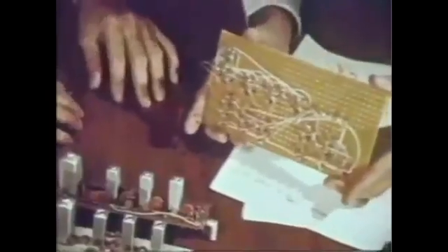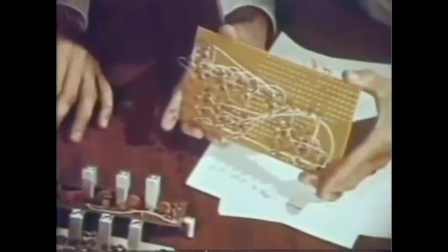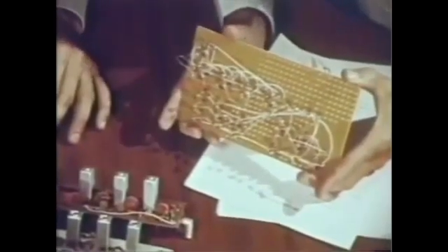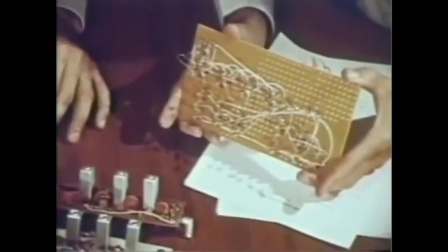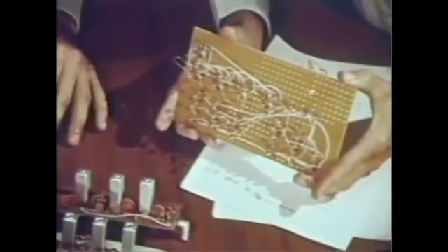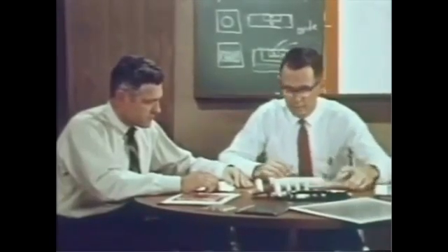On the breadboard, we have separate transistors and other components, all actually wired into a working circuit. The purpose of working with the breadboard is to try to optimize the numerical value of each of the components in the circuit. Once this optimization has been achieved, the next job is the design of the masks, which will be used to make the integrated circuit. Harry, I wonder if you could cover some of that work.